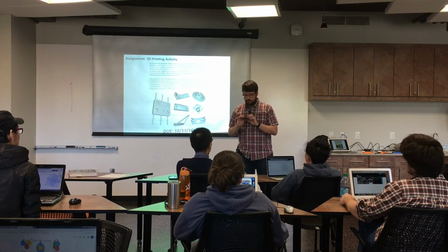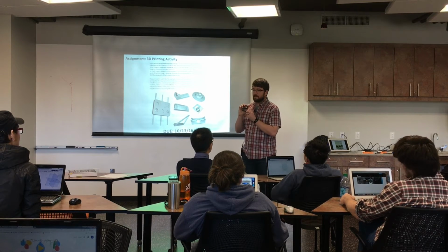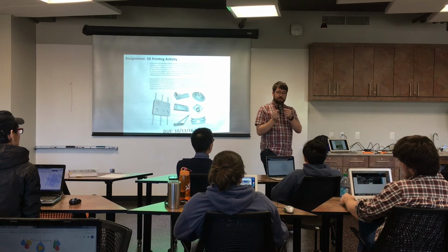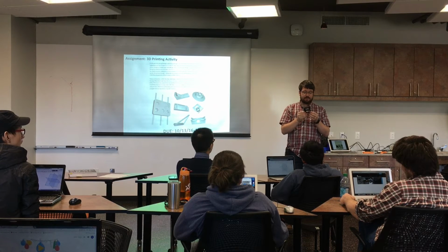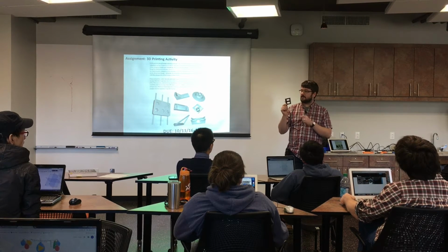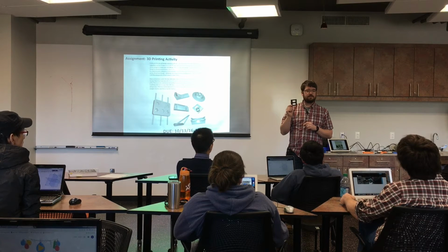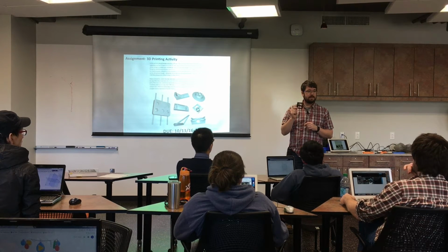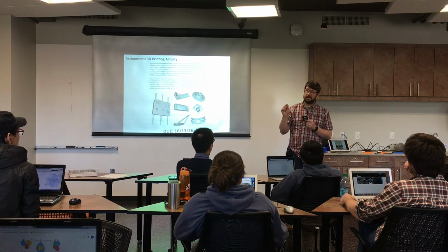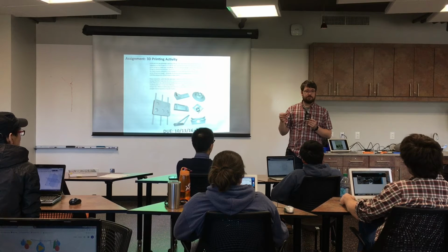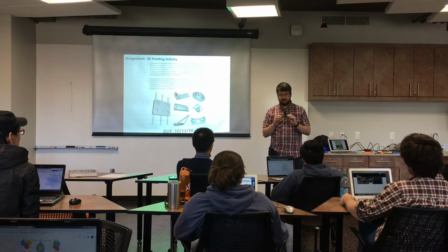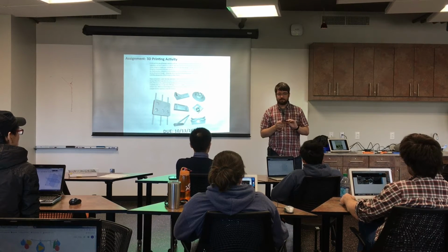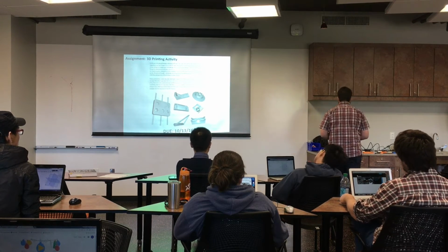You can get these little brass inserts from McMaster-Carr. If you make the hole in the plastic the right size, you hold this brass insert on there and melt it in with a soldering iron. Now I have brass threads melted into the plastic, and those threads won't wear out. So it's a good way to secure stuff together in a stronger way. These are pretty cheap, and you can get them in everything from number 4 screws, which is what these are, all the way up to 3/8 inch bolts. But I don't have a soldering iron big enough to melt those in, so if you do that, good luck. But anything small like this is pretty easy. So keep in mind that those exist.